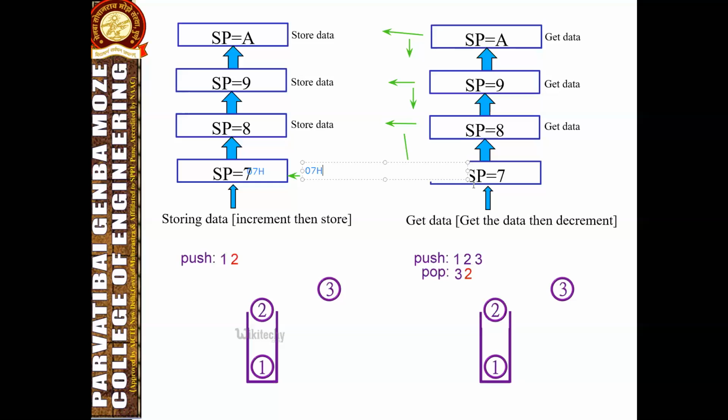If the program needs more than 24 bytes of stack, we can change SP to point to RAM locations 30H to 7FH. So normally the stack is placed at a higher location in the internal RAM to avoid conflict with the register banks and the bit addressable RAM area.